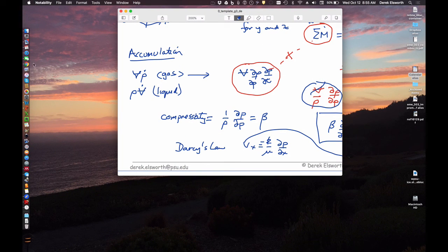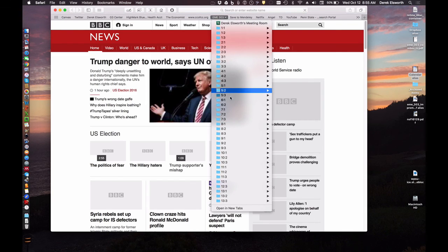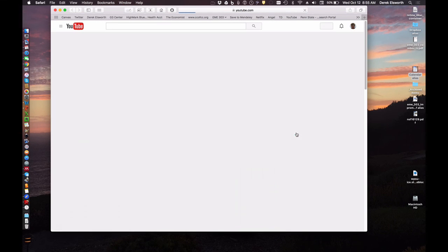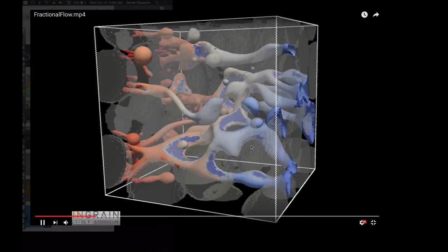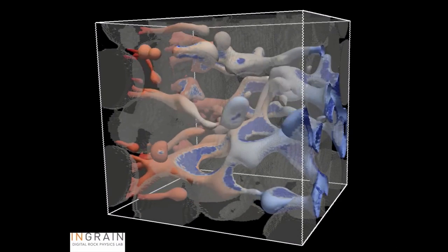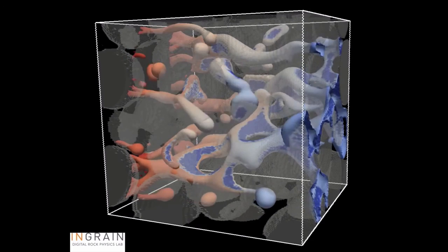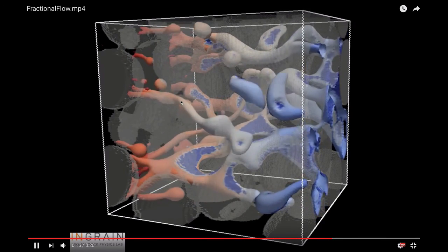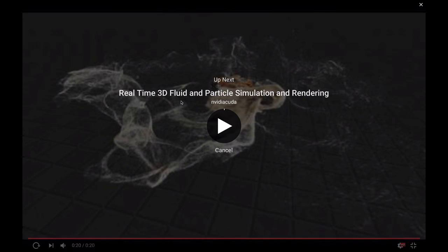And so this is exactly what we've talked about, for those of you who came in a little late, or maybe we started early, was that if we look at this behavior here, then this is exactly what's going on in this particular system. So this is this looping system, upstream pressure red, downstream pressure blue lower, and that's what's driving flow across the system. Viscous friction along the walls of these pores is what's included in Darcy's law to give us this resistance and flow loss, and that's what's represented in the system.